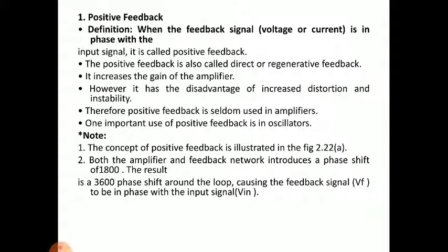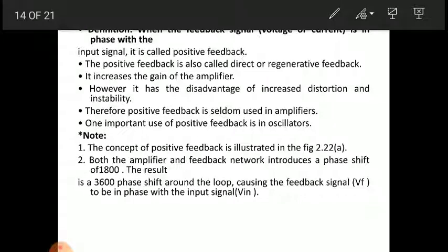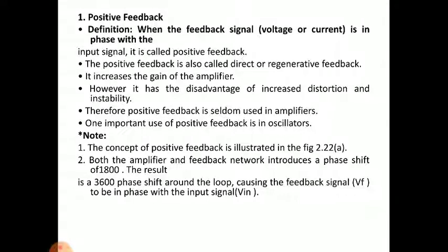So one important use of positive feedback is in oscillators. This is a very good application of positive feedback. In oscillator circuits, in order to generate waveforms continuously from a small portion of input signal, that is from the DC sources, we get a continuous AC. In that case we need positive feedback.